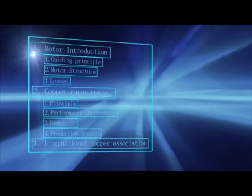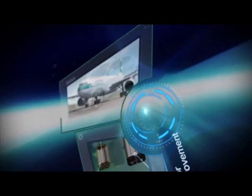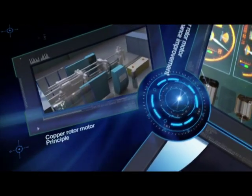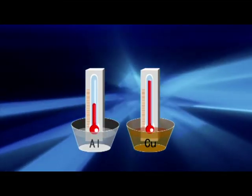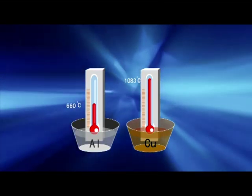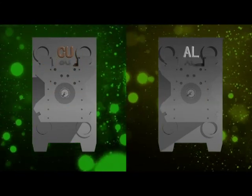Production process. Despite its many advantages, the difficulty of producing cast copper rotors has historically impeded its widespread use, which is why aluminum rotors are so prevalent today. The difficulty in producing cast copper rotors lies in copper purity and a high casting temperature of over 1,100 degrees Celsius, which has been problematic for the die in the pressure chamber of casting machines. Aluminum, however, requires only 700 degrees Celsius for casting.